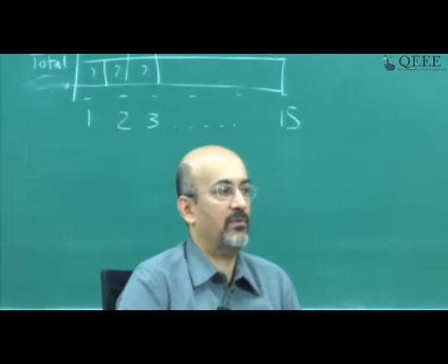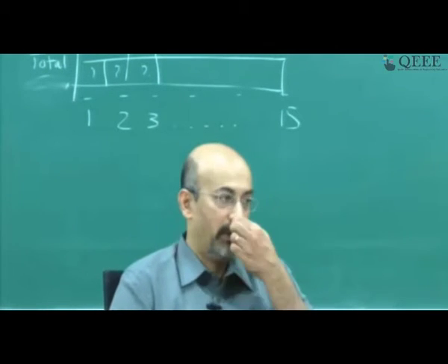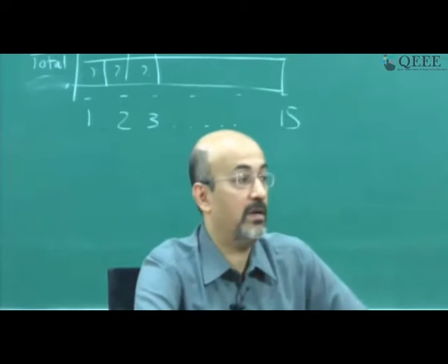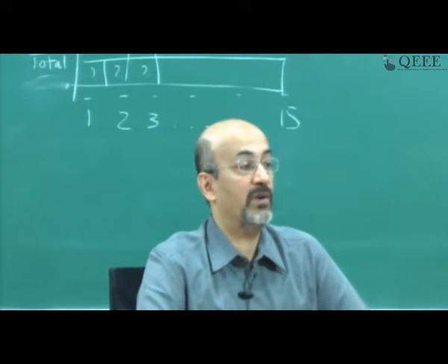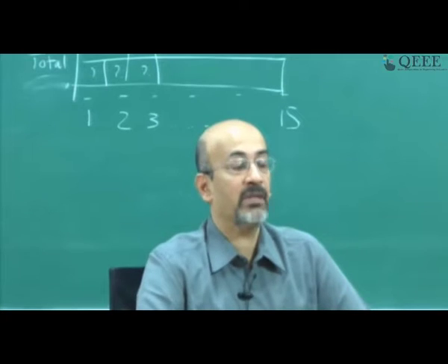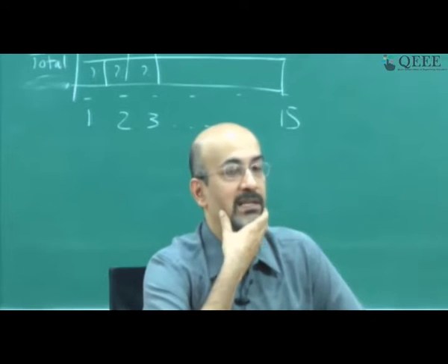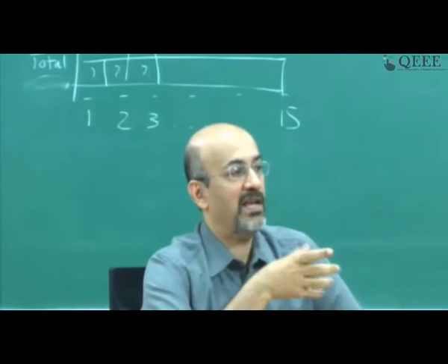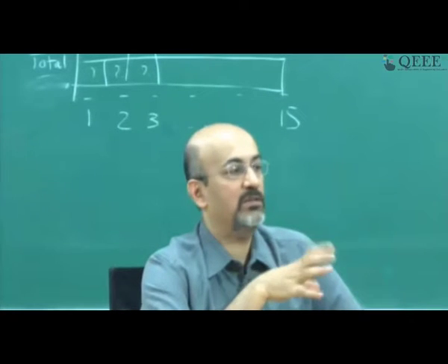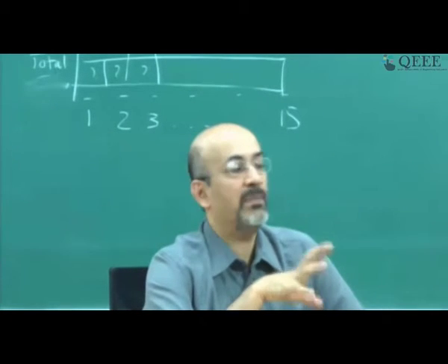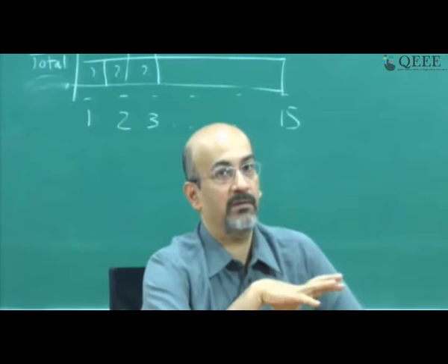Primavera does have fairly good algorithms to do this kind of not only over allocation but also what we call leveling, and leveling to the profiles which we would want to have. So again, like we discussed yesterday, the time we are putting here is absolute time. We are just using days and numbers, but calendar time also becomes important.